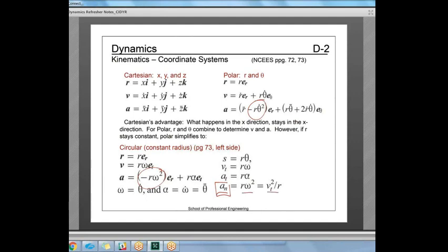But basically what you need to know about centripetal acceleration, or that normal acceleration, is it's what gives rise to the tension in a rope when you're swinging a rock around your head, which of course we do every day. It's R omega squared or V squared over R. How can it be both? Well, V equals R omega, as it says here. So I can take these two V's and call it V squared equals R squared omega squared. And I can take V squared over R and turn that into R. Oops, I don't know why I wrote a 2 there.